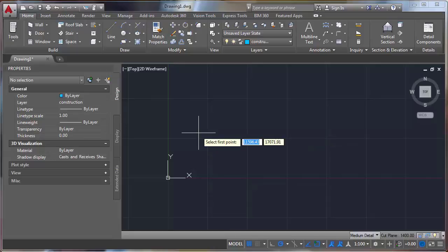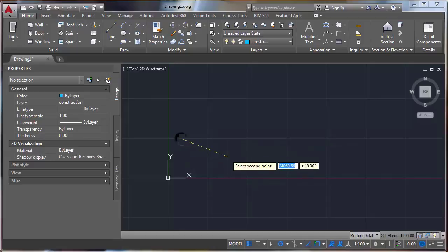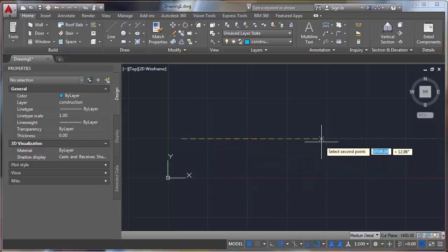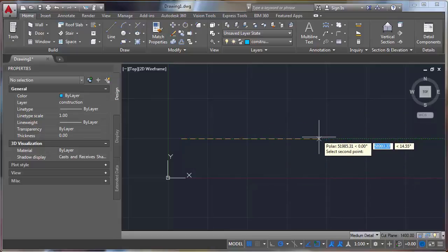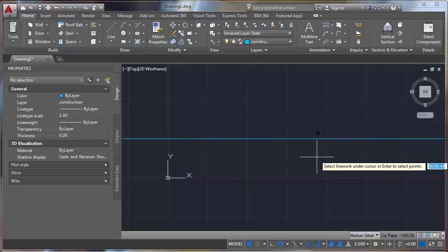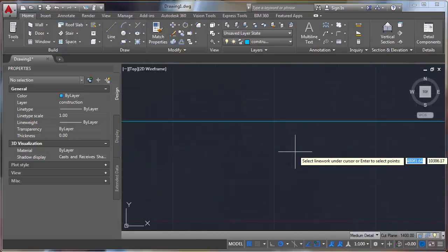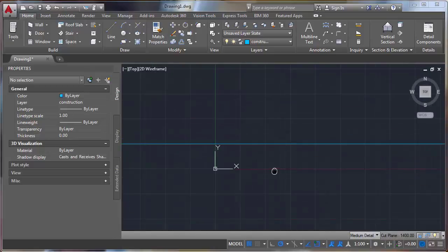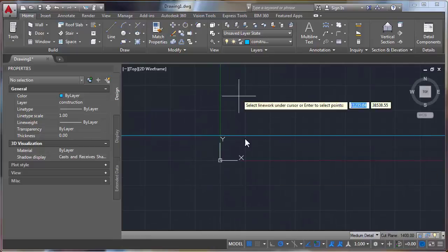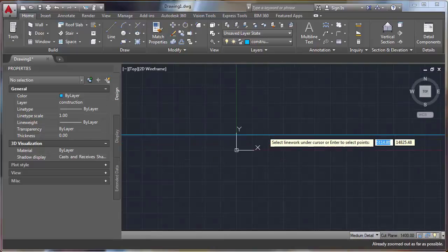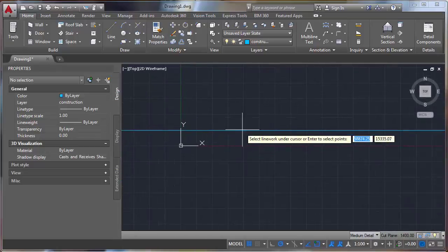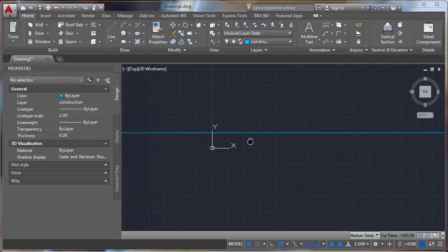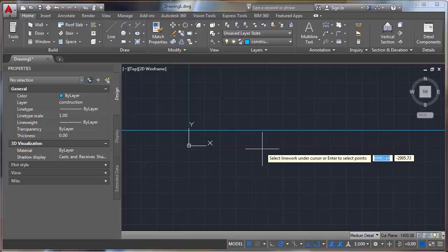So I'm going to hit spacebar. And now you'll see it'll want me to select 2 points. So it gives me this little graphic feedback. What I'm essentially doing right now is creating a ground line for the wall. So when I click the second time, you'll see I now have an infinite line in the screen. I'm moving in and out with the wheel, zooming in and out, and clicking the middle button or the wheel to pan to move this thing around. So learning to navigate quickly is key. So you see I've actually made an infinite line. I can use this for the ground, right?